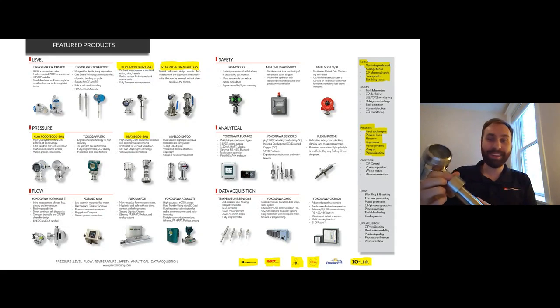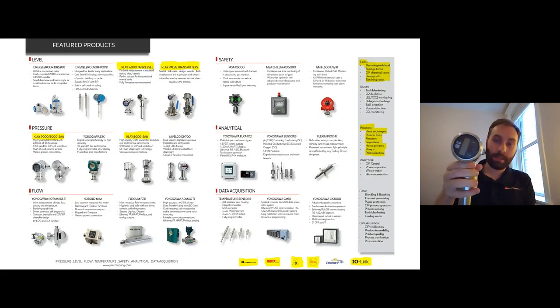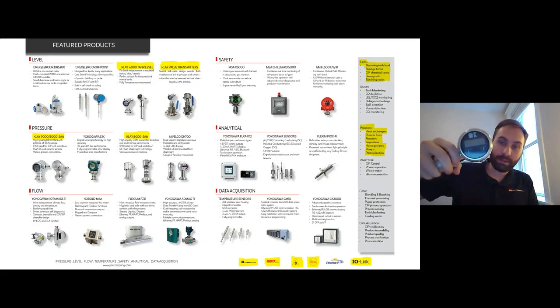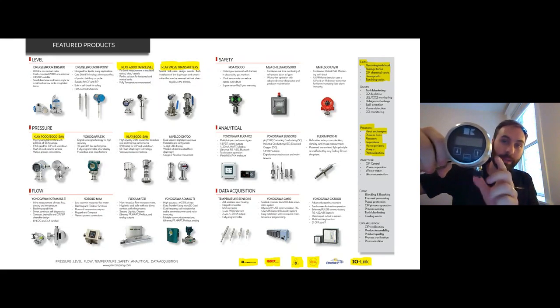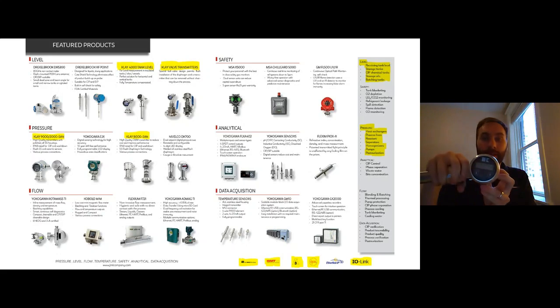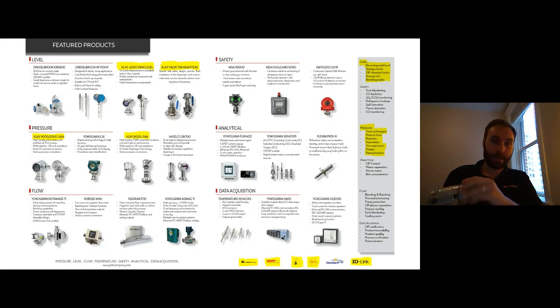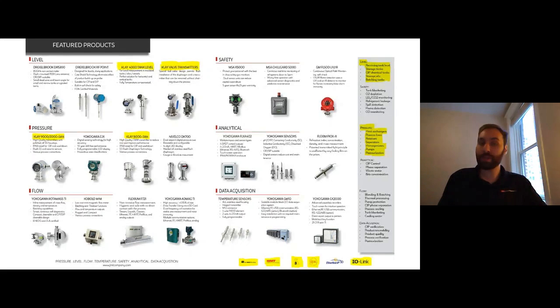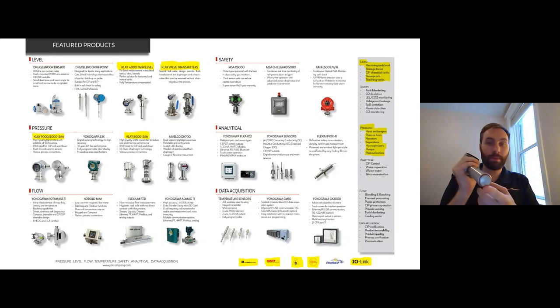I'm hoping that you can hear me and also see the transmitter that I'm holding up. This is commonly used in the dairy industry. There's the diaphragm, a pretty common dairy connection, and the display, which you can adjust however you want to read the level. Let's say you have the tank installed this way, you can move that display around. The pasteurization process, for those who don't know, has fast changing temperatures and fast changing pressures, and it's usually small tanks. So you don't have a lot of room to put a transmitter on there, and having the right size diaphragm is very important. Again, here's the display. I'm just going to twist it to show you. That's what the company was born out of: compensating for fast changing pressures and temperatures, and having to use small diaphragms in some cases.